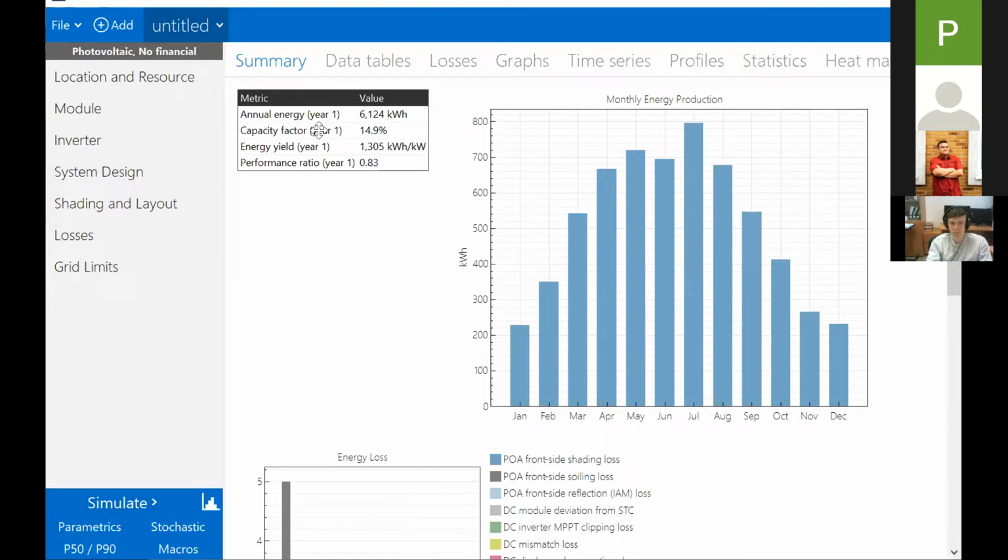On the other hand, one of the big problems that you have with desert installation of PV is that it often is operating at very high ambient temperatures. And we're going to see when we look at photovoltaic technology that typically the efficiency of a PV system decreases with increasing temperature. And that's a major issue for system performance.